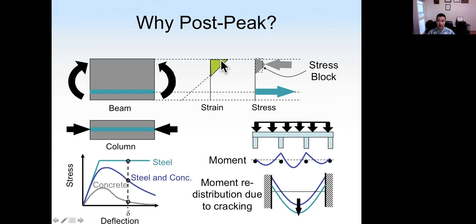If the top portion is damaged, the whole concrete will not fail, and the stress will change to something like this. Even though the stress in the top portion becomes zero, the concrete can still resist some of the load. So the concrete together with the rebar will resist the moment after a certain part of the concrete cracks.